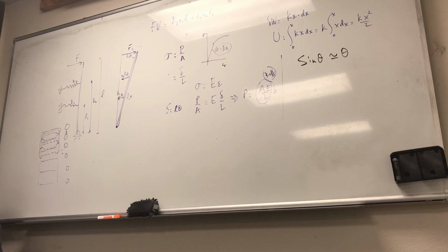So this is a multi-story building subjected to an earthquake, assuming that the mass of the frame is negligible compared to the masses of the floors. The building can be modeled as a multi-degree of freedom system as shown. The masses of the various floor levels represent the mass elements, and the elasticities of the vertical members denote the spring elements.